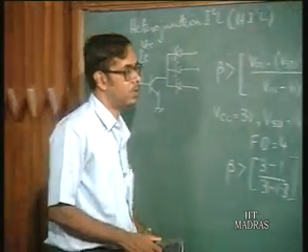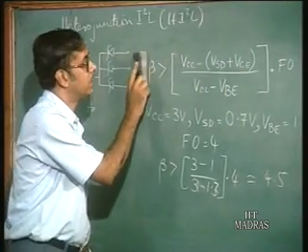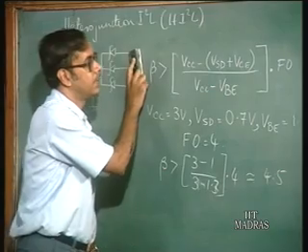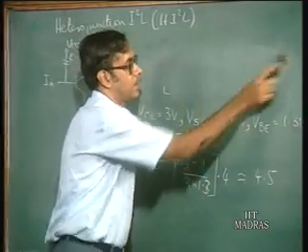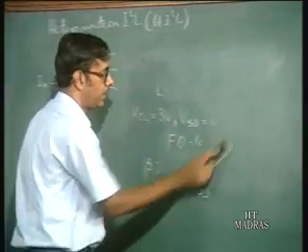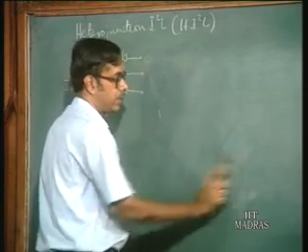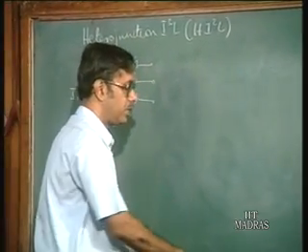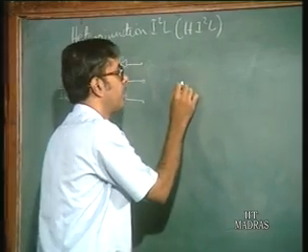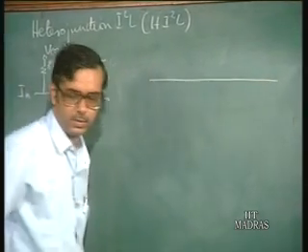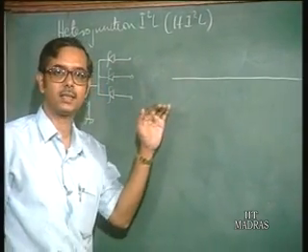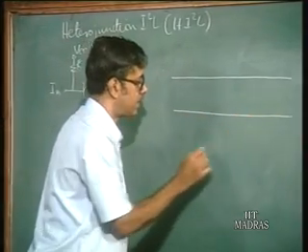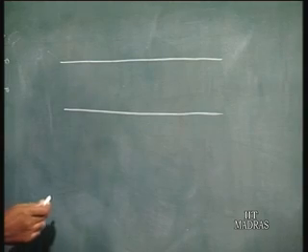Now, what is the structure? I will just give you the cross sectional view of this device. How does it look? Well, most of the compound semiconductor devices are fabricated using epitaxial wafers, where most of the layers used in the fabrication of the devices are grown epitaxially. So the processing after that becomes quite simple.